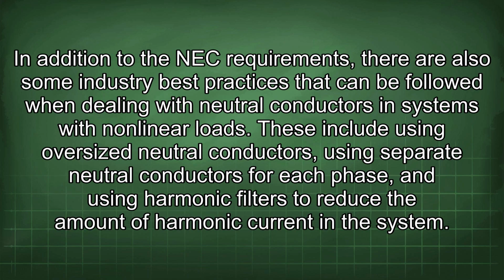In addition to the NEC requirements, there are also some industry best practices that can be followed when dealing with neutral conductors in systems with nonlinear loads. These include using oversized neutral conductors, using separate neutral conductors for each phase, and using harmonic filters to reduce the amount of harmonic current in the system.